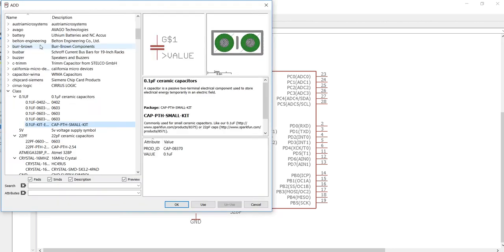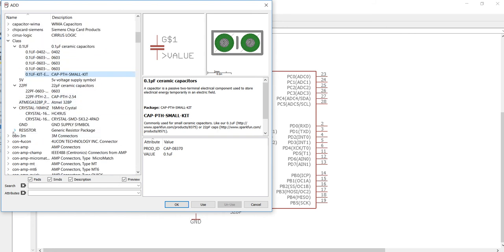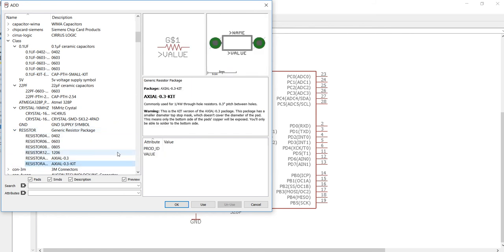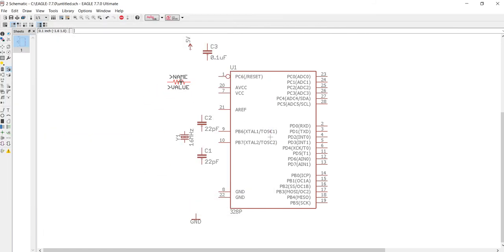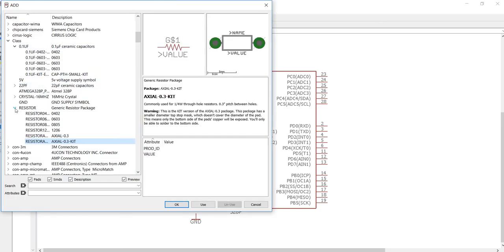Now we want to add in some header pins, some 0.1 inch headers, so that we can actually plug in things like an FTDI or breadboard with this, right? Actually, let's get our resistors in there first. So we do need a resistor which comes off of the reset, and let's get those. Let's collapse these real quick.